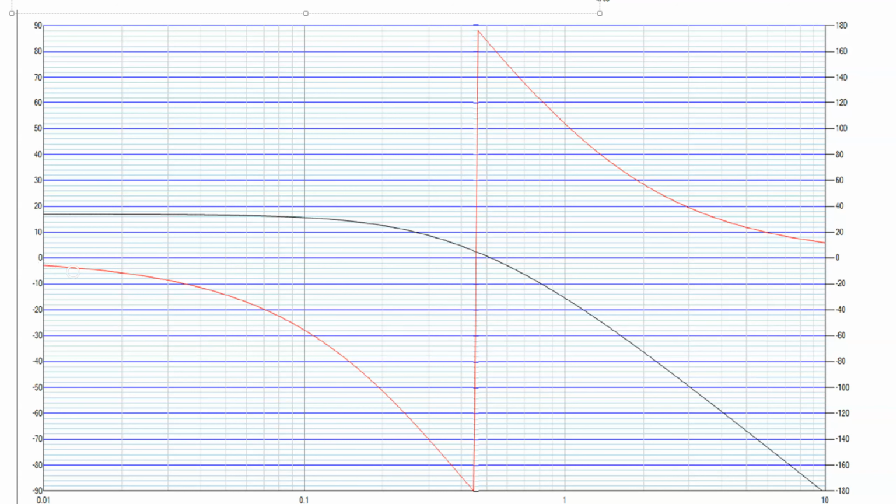The phase curve is negative and goes down to this point. Here you see a phase wrapping step. So all values which are deeper than minus 180 are added with plus 360, a full period, to a positive 180, and it is continued here in this region. So you can read that these values are not the actual correct values. For these values, if you want to have the correct phase, then you have to subtract 360 degrees.